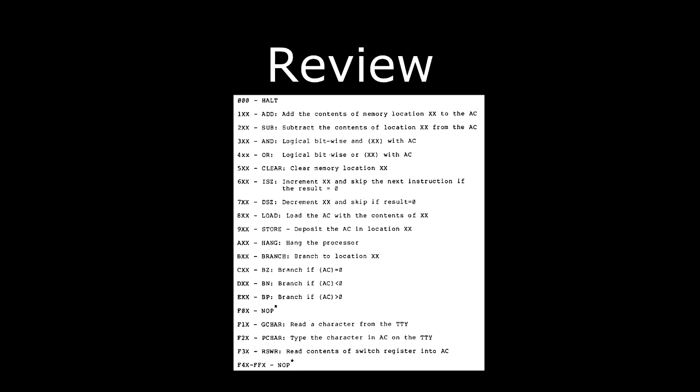Stupid computer. Let's start by looking back at the original instruction set, and as you recall, we were limited there by the amount of microcode memory available. So it's not a very robust instruction set, shall we say. It's rather wasteful, and there's a lot of unused potential opcodes in there. Or wasted opcodes. If, for instance, we look at halt, which was opcode 0, there's 8 wasted bits there that could be used to address a memory location, for instance.